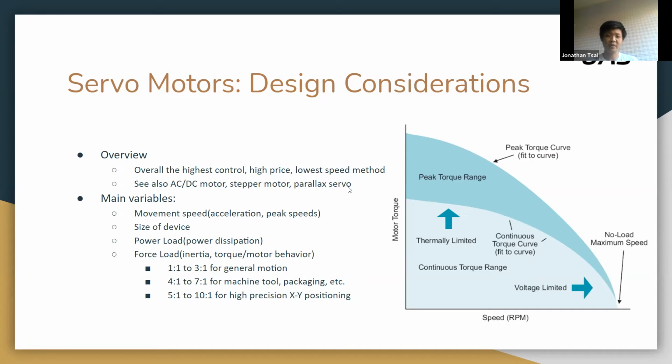All right, then. So now that you've realized that you want a servo, here are the main things you want to consider. Is the servo fast enough for your purposes, right? Will it take too long to move around? Will it be too fast, which I doubt it ever will be? Is the servo a reasonable size? Can you fit it in, say, the UGV at an appropriate time? Is the power reasonable, right? If for some reason you only have a 9-volt battery and you need way too much power, the servo won't be good. Likewise, in the other direction, if you require a nuclear reactor to power your servo and you need to fit it on the UGV, that's probably not a good idea, right? So you want to make sure that you have a good power fit with your servo, okay?